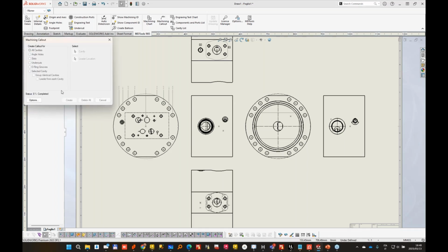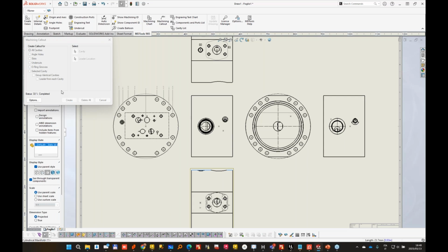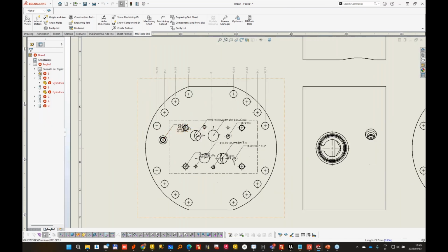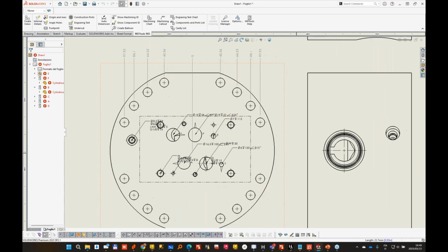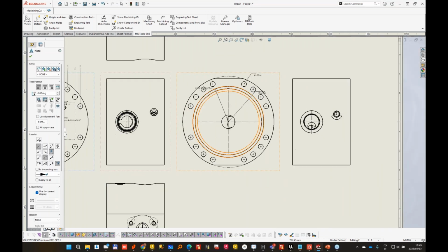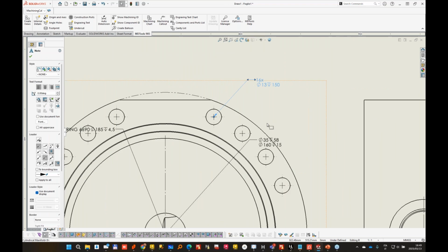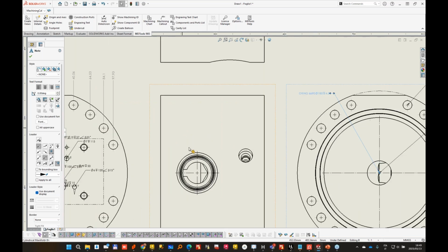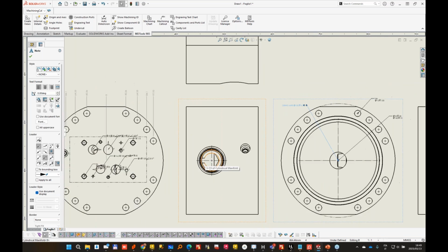If we do machining callout at this stage of the block, now the machining callout will show only for those cavities that will have a face. So it will show the machining callout on all the bolts. Those are grouped 16, 13 by 150, all the drills. But in this case, MDTools is not able to create the machining callouts here because there is no face.